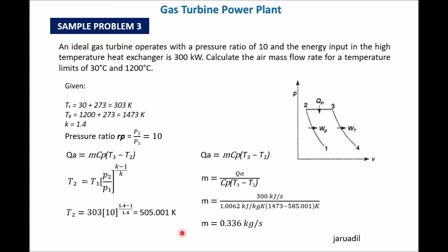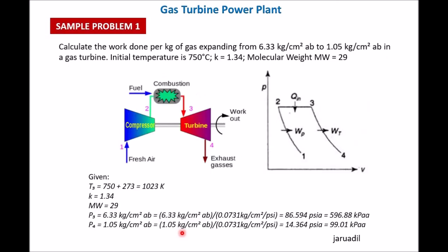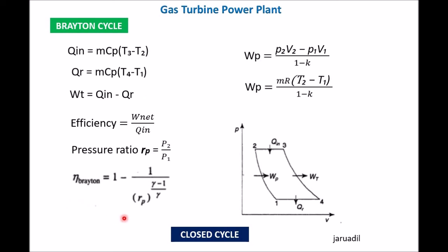We have here 3 examples. There are still many things we can discuss about turbines. For example, finding the efficiency. You use the equation for the efficiency. If the problem is to find the efficiency, this will be your equation. Now, the turbine work can also be found using Q added minus Q rejected, but this is used in some special cases where you know the QR. If you cannot determine the QR, you use the turbine work by the isentropic process 3 to 4.